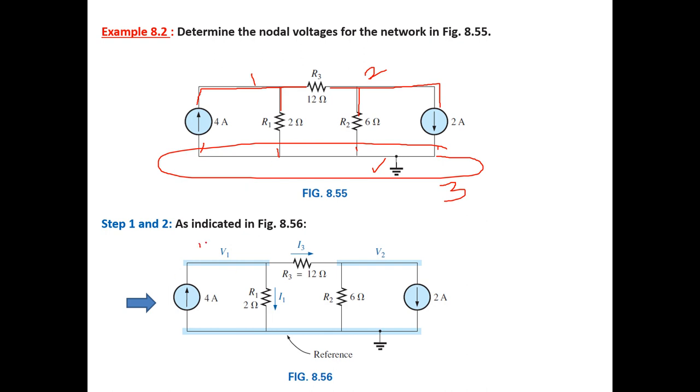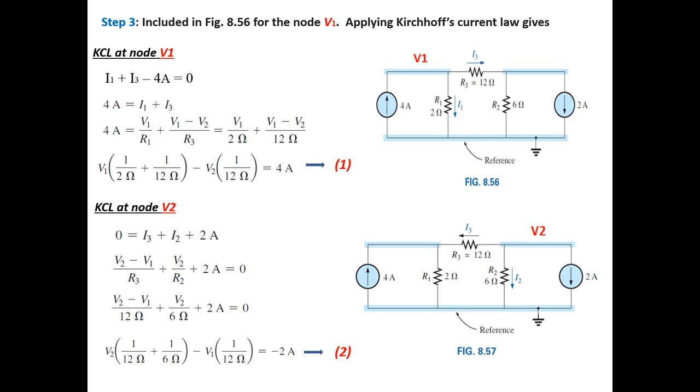So again, I will name it V1 for node 1, the voltage here, V2 for node 2, and this is our reference. We know it's 0 volt. Okay, so let's work with each node individually. I will work with V1 here, but of course I have V2 here, do not forget it. I will consider node number 1 only, and we will assume it as the highest point as we agreed.